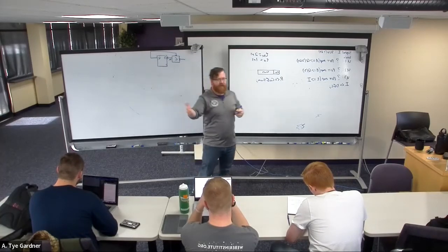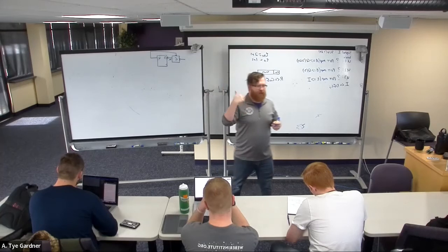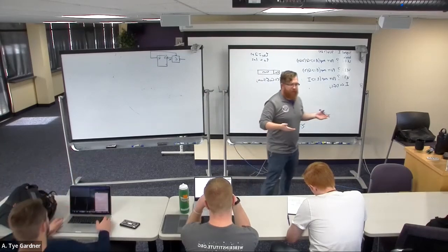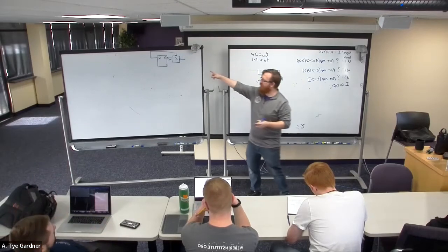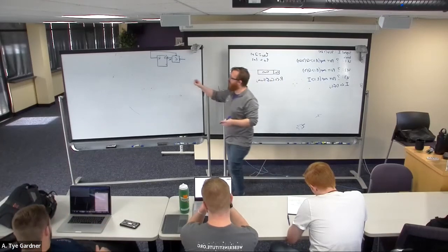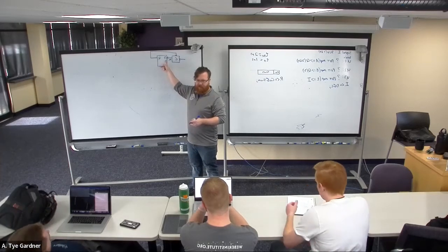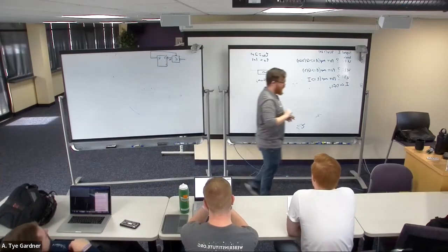So it becomes a race. Who wins? Do we get the next value or double clocking the old value? And we don't know. So we have a speed limit because of the speed of our devices, the speed of our combinational devices combined with the setup times is going to determine how fast we can go.